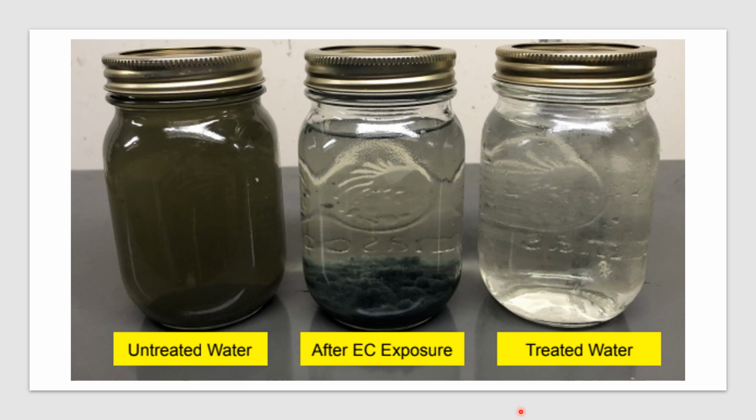In the electrocoagulation system, the water is passed through a series of oppositely charged plates. The system converts the 480 volts alternating supply current, rectifies it to direct current, and feeds it to the plates in a controlled fashion using a PLC. In this way, the electrical charges are imparted to the particles in the water, causing them to bind together, become larger, and fall out of solution.